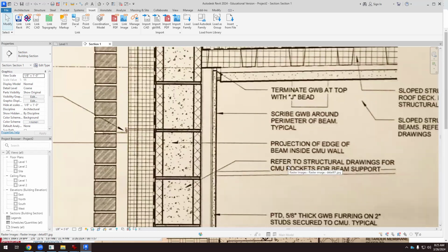It will help a lot because, yeah, I mean, this project has like 100 or 200 sheets. And yeah, go to the structural drawings. But yeah, it doesn't do any harm typing the thickness of this concrete masonry unit. Anyway, the brick is always standardized. Well, usually bricks are 4 inches by 8. I think this is a short dimension, so that should be like 4 inches. So if this is 4 inches, we're going to make up the rest of the dimensions.